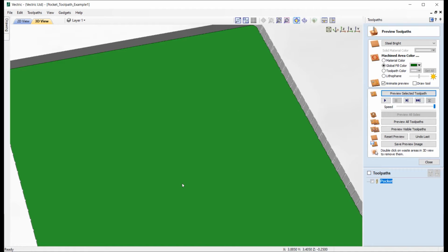So you'll notice that where we've cut the pocket with a 40% step over, and in the raster strategy, we're actually left with cusps because we are using a round tool. Now that's okay, but I might want to make a nice smooth edge that actually follows the vector, and that's where the profile options can help.